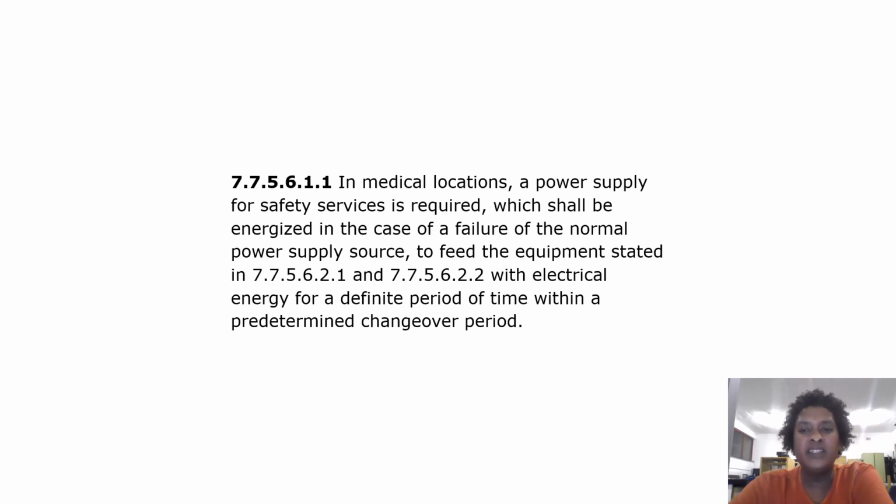In medical locations, a power supply for safety services is required, which shall be energized in the case of a failure of the normal power supply source to feed the equipment stated in 7.7.5.6.2.1 and 7.7.5.6.2.2 with electrical energy for a definite period of time within a predetermined changeover period.